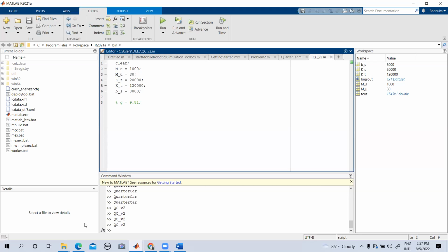If a passenger weighs a maximum of 100 kilograms, and there are 5 passengers in the vehicle, that accounts for 500 kgs plus the weight of the chassis and the other components, the engine and all. We can specify the sprung mass, and the wheel base mass we can also calculate, right?